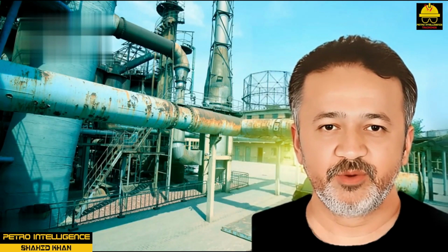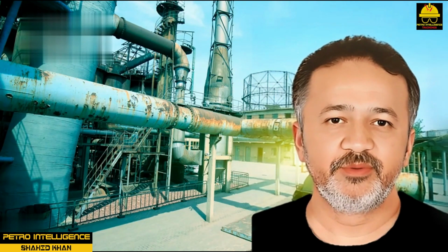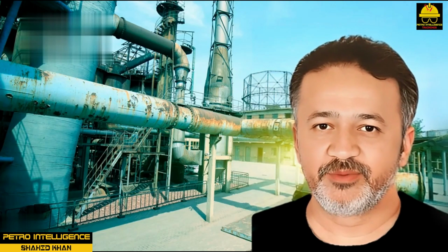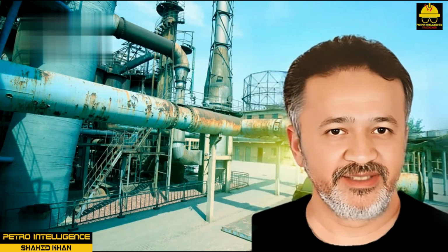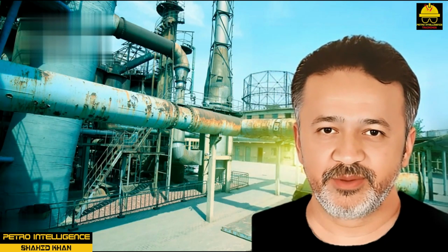Entry into the high flare radiation area must be by permit only and must be coordinated with the operations department. Anyone in the area must be in constant radio contact with the control room. Flare stacks are provided to burn vent and waste gas from the units. Normally the waste gases are burned as fuel gas, but at times when a unit upset occurs, large quantities of gas must be disposed of at low pressure to the flare.